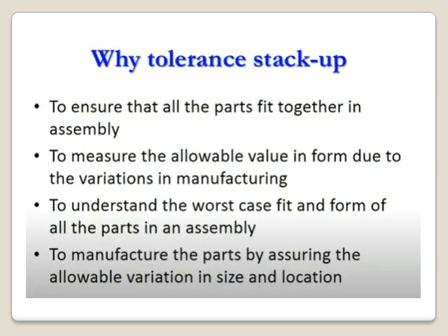Why tolerance stack-up analysis? To ensure that all the parts fit together in assembly, and to ensure the allowable values in the form due to the variation in the manufacturing. Another, to understand the worst case fit and form of all parts in an assembly, and to manufacture the parts by assuring the allowable variation in the size and location.